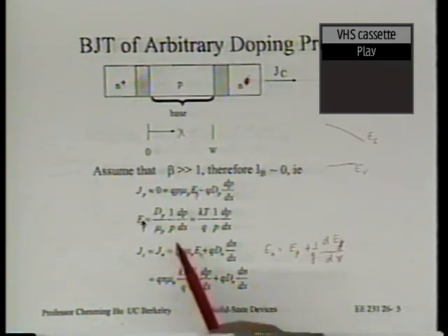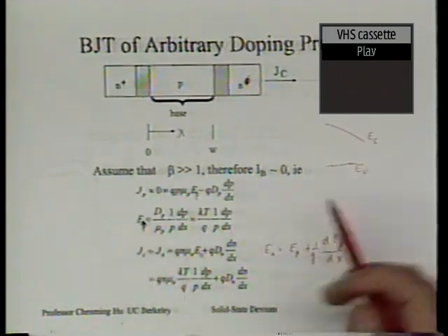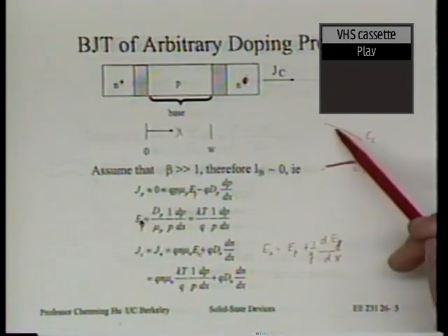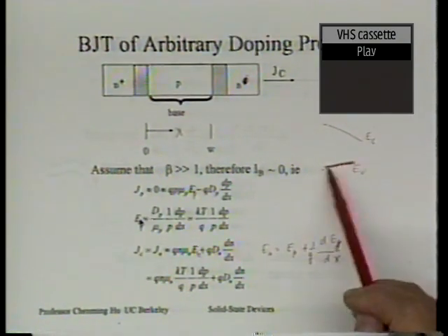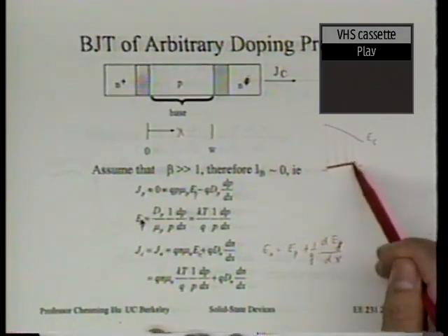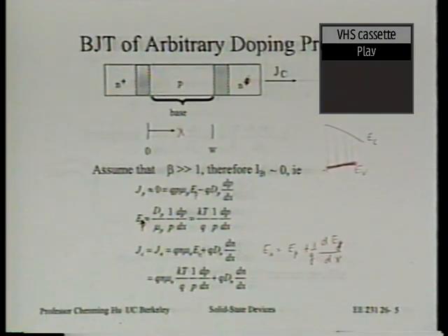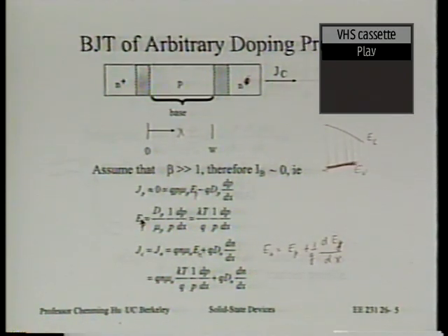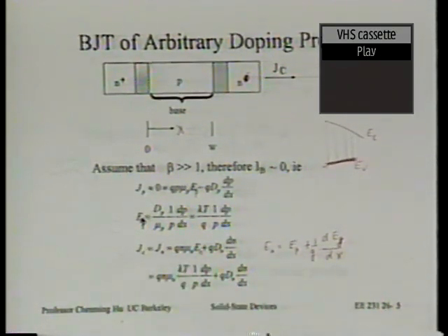In other words, the electric field experienced by the hole is the slope of EV. We already have some of that. So what's the slope of the EC? Well, it must be that same slope as EV plus the gradient of the change of the gap between the two. Is that right? So assuming that you know this, because you're the engineer that designed that silicon germanium profile, suppose, then you just add that into this equation and see what you can do.